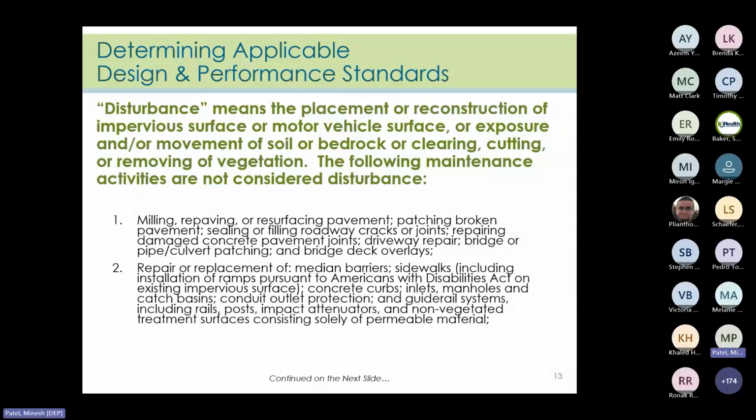We have previously discussed the definition of disturbance, which means the placement or reconstruction of impervious surface or motor vehicle surface, or exposure and/or movement of soil or bedrock, or clearing, cutting, or removing of vegetation. There are certain maintenance and repair activities that do not qualify as disturbance in the stormwater management rules, however, as they are minor repair activities for the purposes of 7:8.